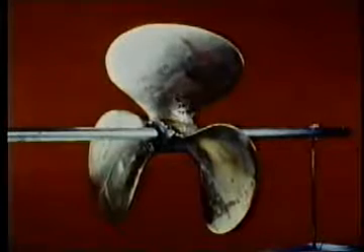The pressures associated with collapse are high enough to cause failure of metals. Here is cavitation damage on the runner of a large hydraulic turbine which operated under cavitating conditions for an extended period of time. This propeller operated under cavitating conditions for only a few days. Similar damage can be produced on pump parts, such as this impeller of a pump for high-temperature liquid sodium, and in the low-pressure regions of hydraulic structures, such as this large power dam spillway tunnel.